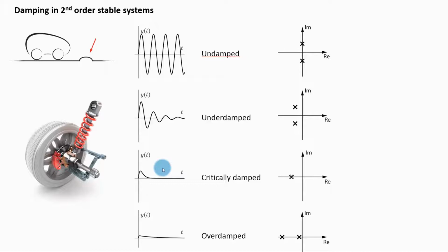And that is why in the car suspension we do not only use a spring to suspend a wheel, but we also use a damper. The damper is the thingy you can see inside of the spring. It is essentially a cylinder with a piston that resists motion. The addition of the damper into the system is equivalent to the addition of some friction or energy dissipation.